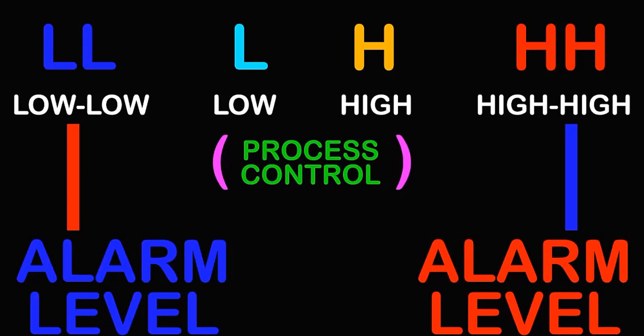When the temperature gets below 70 degrees, we turn our heater on and we latch it on so that it stays until our temperature reaches a high set point, and we'll set that high at 80 degrees. So as long as our temperature doesn't fall back down to low, our heater won't come back on, but it'll bounce, assuming that the ambient temperature is of course below our low set point. We'll say it's 60 degrees outside.